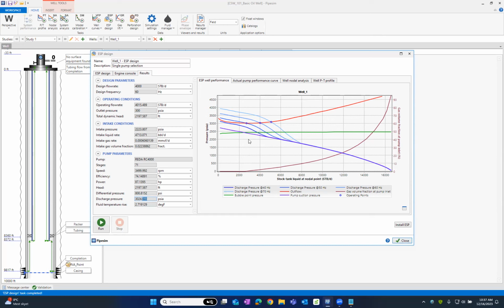In this case here, this is the IPR at the location after the pump, okay, with the ESP. Here, this is the pump suction pressure, which means that this is as if there is no pump.